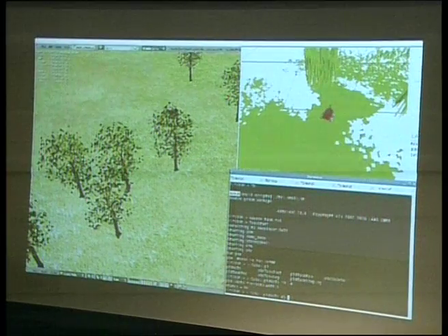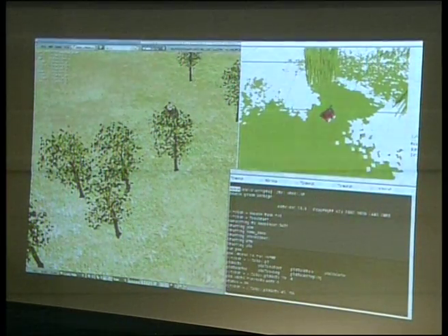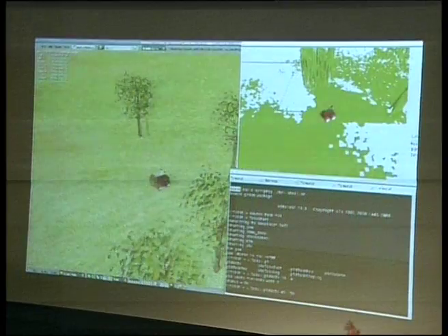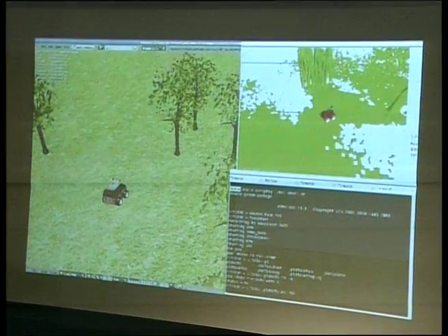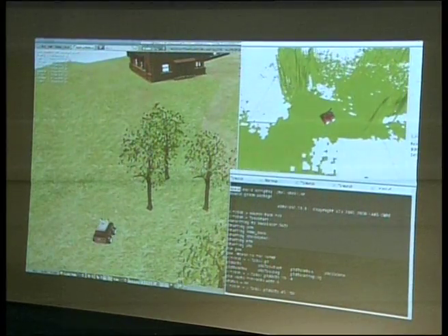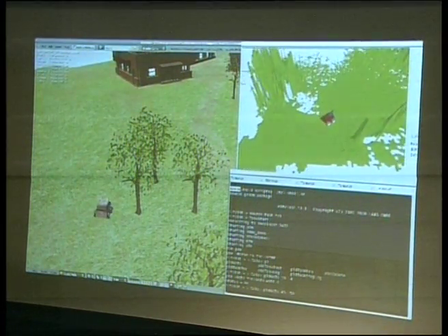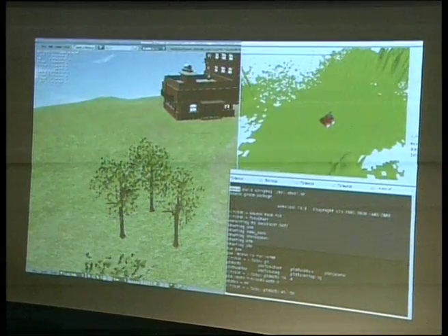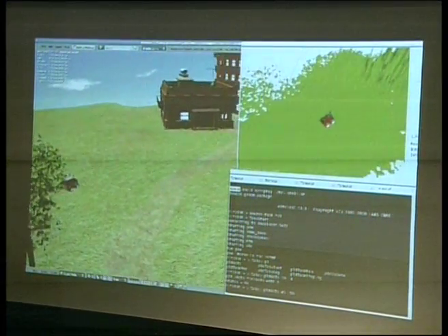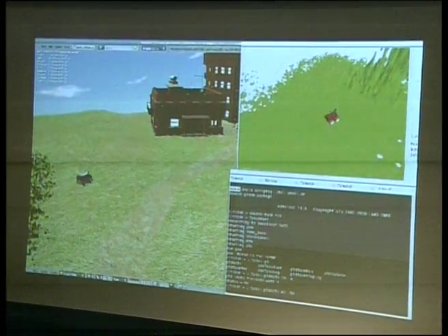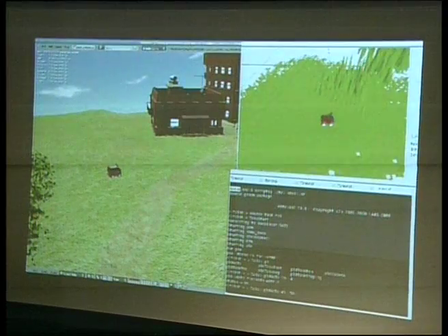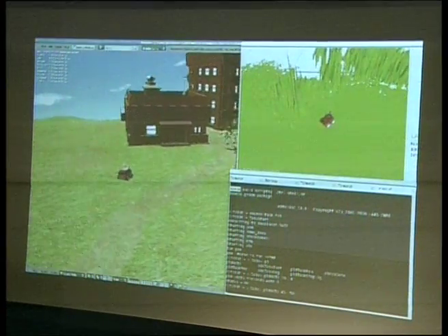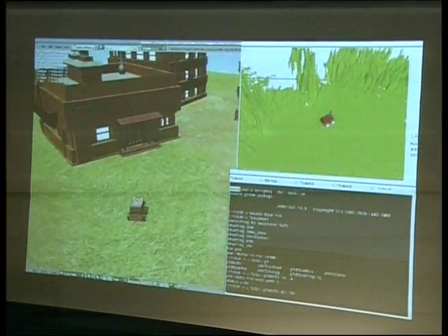We really do take 2 images from the cameras on board of the robot and compare them to identify the differences. That's how we build the 3D mesh of the environment, the digital terrain map. And that's what it uses to navigate. It's kind of ugly, but that's how it works. That's how the real robot understands the world, and it doesn't need much more information than that. It just knows that the flat surfaces are where it can walk. If there is any jagged surface, it means that's irregular terrain or obstacles, and it will not try to go there.